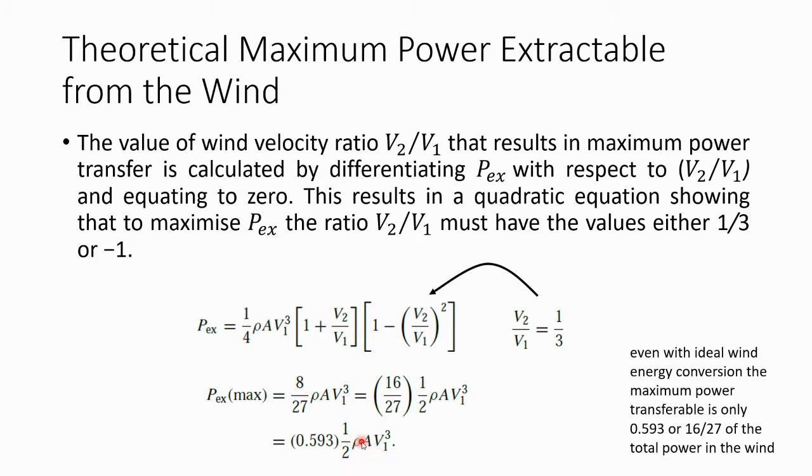But when it goes through the wind turbine and then we extract the power from the wind turbine, because that is the only power that we can connect to the grid. We cannot connect the power from the incoming wind to the grid. We cannot do that. We can only connect the power that is generated from the wind turbine into the grid. Okay, therefore, we are calculating the extractable power from the wind turbine and not the theoretical power from the incoming wind.